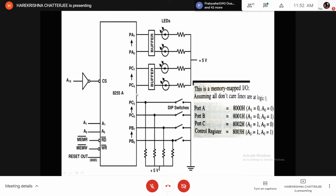The same bit pattern should be shifted to the port C upper part so as to glow the LEDs according to the switches connected to PC0 to PC3. So we should read port C data, the LSB 4 bits we are interested in. We should shift it into the MSB 4-bit part.